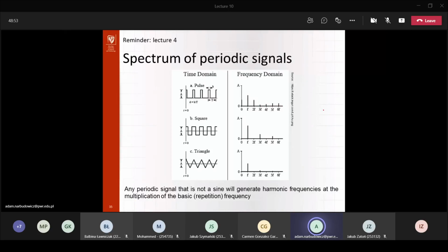So by using a sine function at the input with the compression point, by compressing the peaks of the function, you end up with a non-sinusoidal function, which after doing the Fourier transform will be seen as having additional frequency components. So far, is this clear? Or do you have any questions?